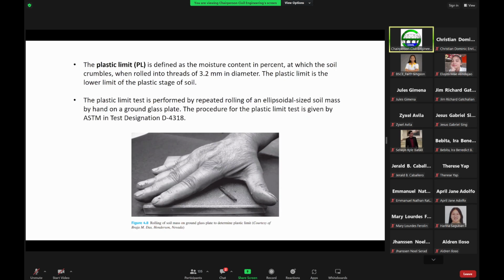Now, again, when we prepare geotechnical reports, we state there the laboratory tests that have been done for that particular project, and the ASTM standards used for such tests, so that whoever reads the geotechnical report would understand that we are doing a standard test, which we can understand.